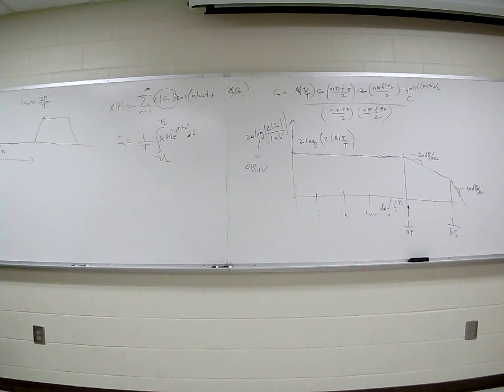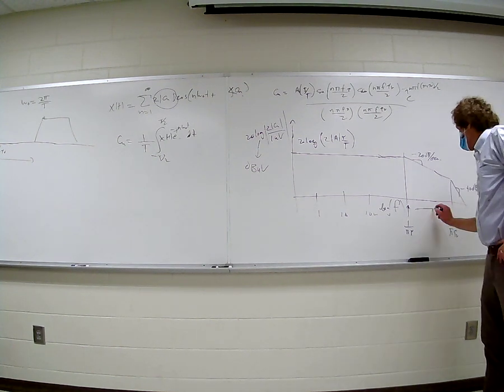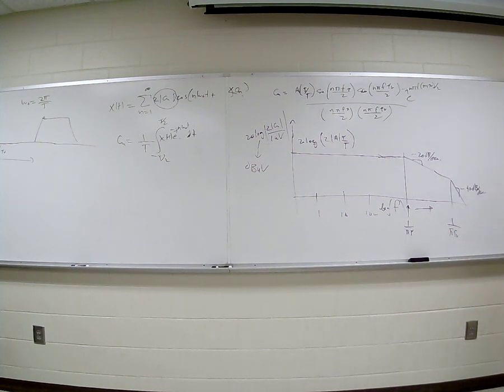Okay, I'm putting it all up there. You've got it on OneNote, but that's the way it goes. This is a logarithmic frequency axis here. That's 20 times the log of 2 times the magnitude of C of n over 1 microvolt, and this is typical. This is the way it's done in EMC. So these are the plots you see.